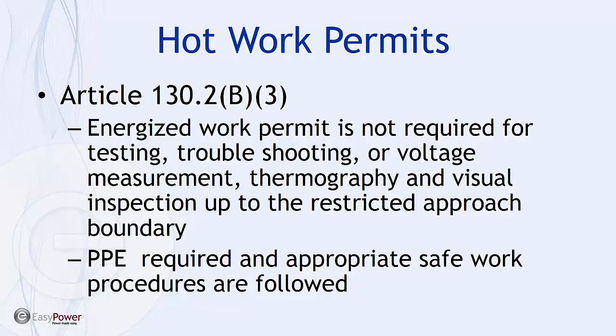So now we may be able to do certain procedures without the necessity of a hot work permit. It's that elevated knowledge and understanding of my system itself, and what adjustments can be made even on a temporary basis, that I want to make sure get incorporated in my procedure for doing hot work. That all of a sudden elevates this discussion from just meeting the letter of the law to being focused on the safety of the workers. And I think that comes across during a discussion with the team about all these elements.